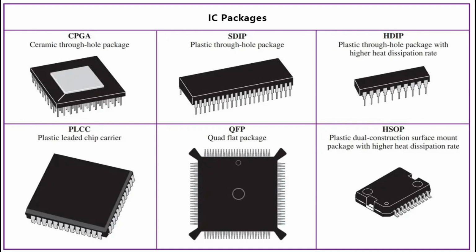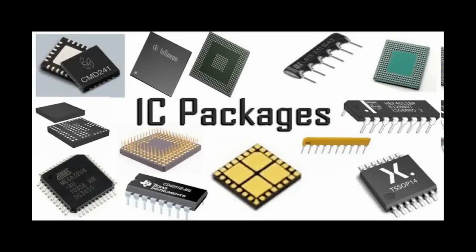7. Sleep modes and power gating. Function: puts certain components or the entire system into low power modes during periods of inactivity. Power gating involves completely shutting off power to specific sections of the device. IC type: power management ICs and features integrated into microcontrollers and processors.